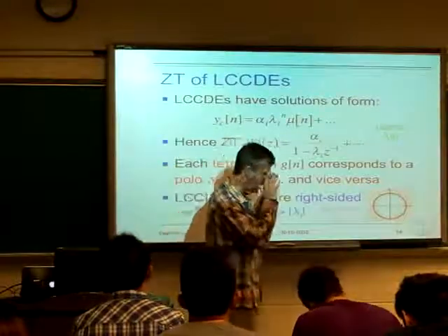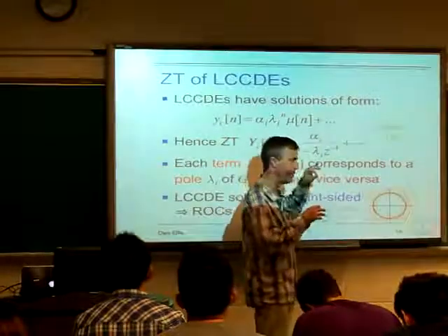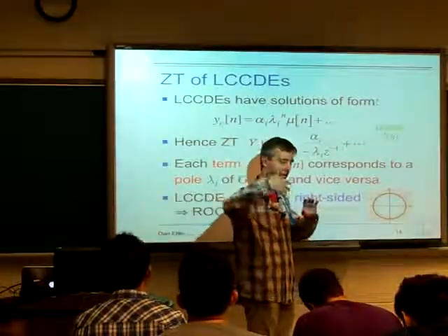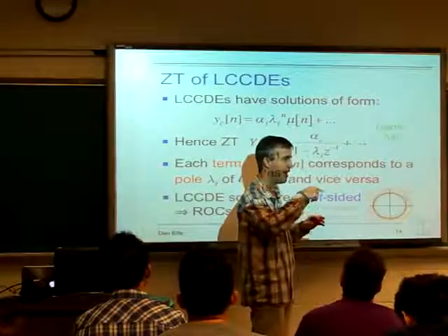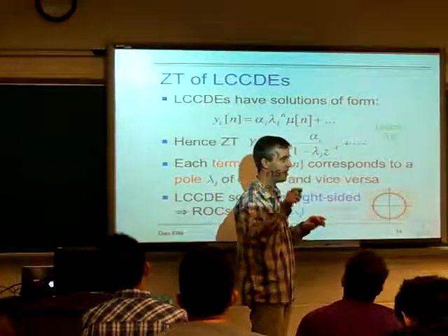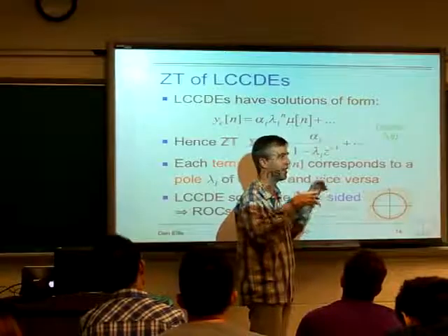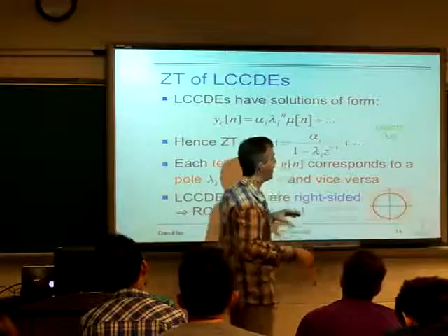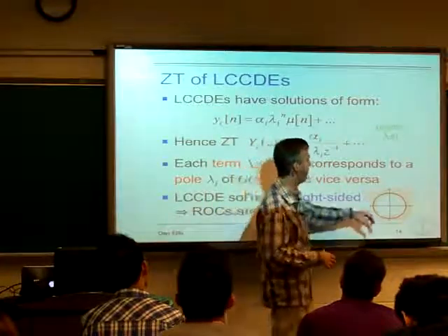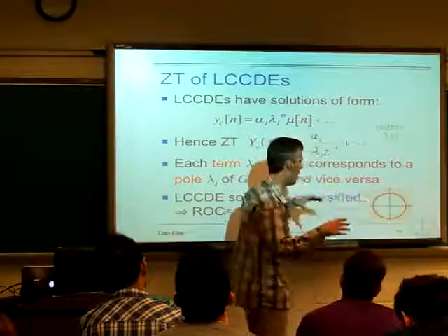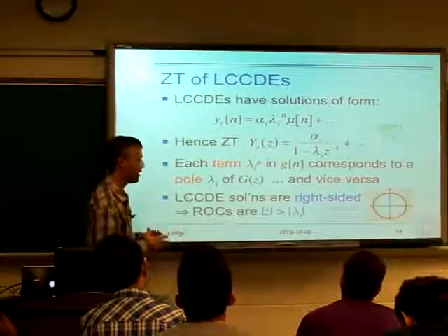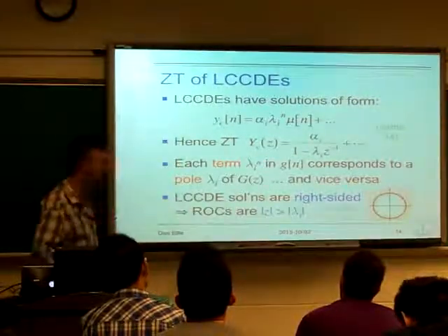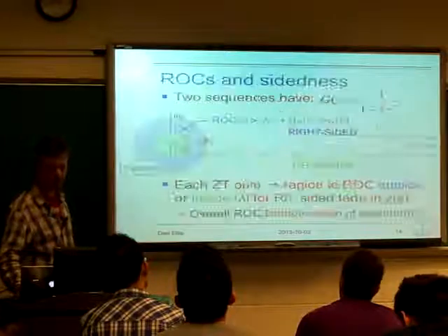There's nothing particularly weird going on there because of the way that Z shows up in the Z transform. If you've got a right-sided sequence, you're taking successively higher powers, which means you're raising Z to the negative of something larger. So you want a large Z, because then when you raise it to negative some high power, it gets very, very small, 1 over Z to the n. It's only when Z gets smaller that you get problems with the convergence. That's why the values of Z with small magnitudes are the ones that cause it to blow up. And so the region of convergence is always the outside of some circle for right-sided sequences.